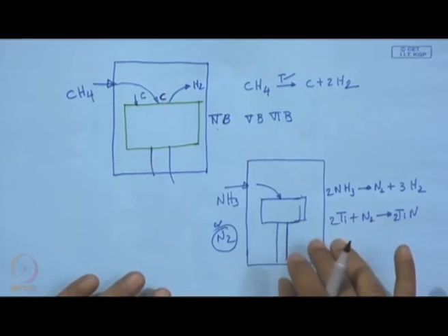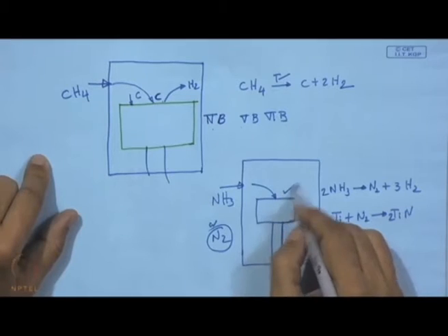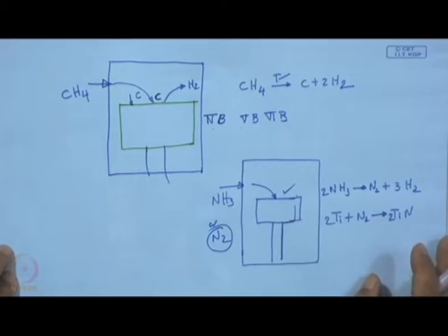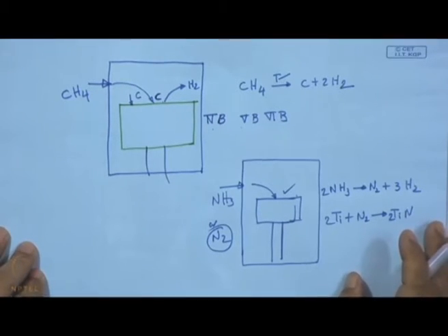This is thermally activated. However, this is carburizing, this is nitriding, but we can also have carbonitriding. The reason is as follows: in this case we need to take advantage of both carbon and nitrogen. If we consider titanium as the metal donor, then we can have titanium carbide, titanium nitride or titanium carbonitride.